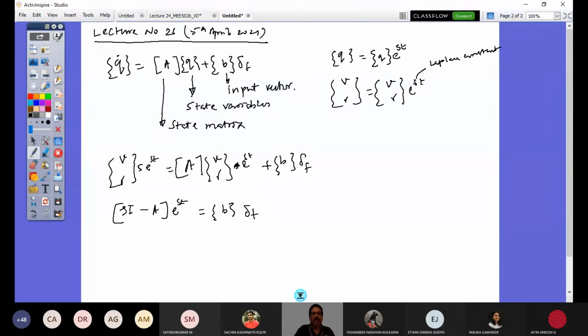Okay, sorry. Let's continue now. This state space form of representation can be useful for two aspects. One is to do stability analysis. Let us look at that separately, wherein we will make the input 0 and then do perturbation analysis, or free vibration study, so that we would be able to talk on its stability. The second one is to get a characteristic polynomial.